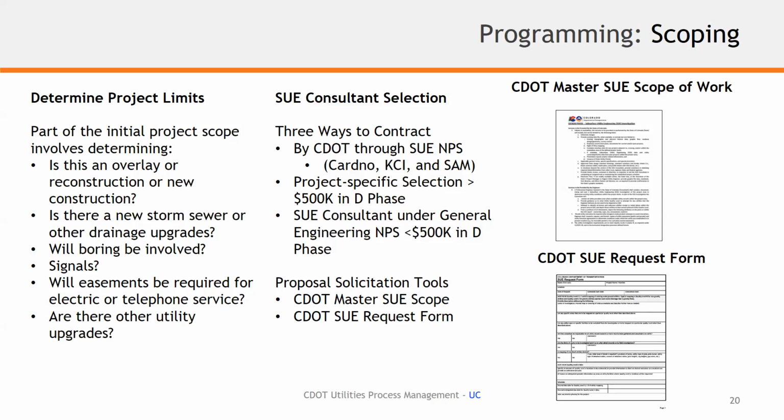So one of the things I looked at here, and that we've come across recently, and it's really also important to understand ownership of the area surrounding the project. Are we going to be widening the right-of-way? Is the ownership adjacent to our right-of-way private, or is it public, or, for instance, federally owned land? Do we own the right-of-way outright, or are we there under highway easement deed?